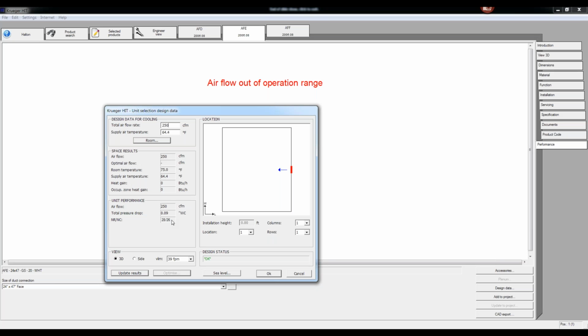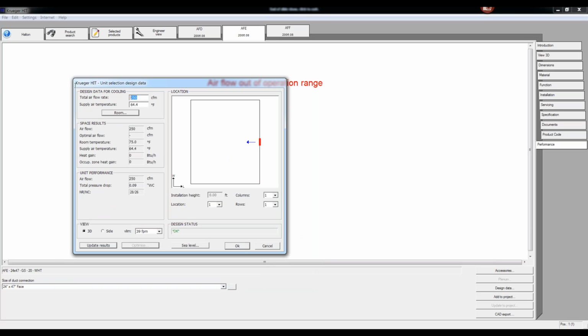So I can tell you right now, based on that NC, that we have too much air, because really it's a little higher. So I'm gonna just step that down to 200, because yeah, NC of 19, that's much quieter. Set that to 60. And again, if you want to increase the number and play around with orientation, you're going to be working in this space right here.